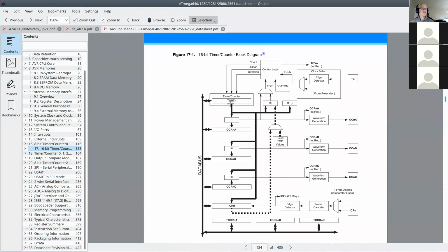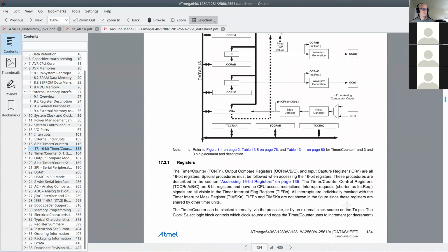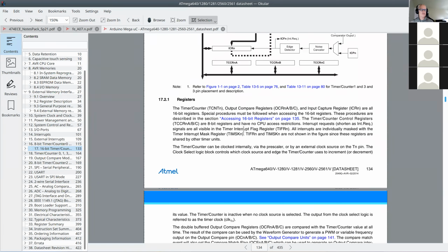And then as this thing's counting, you can freeze it and store the value exactly when a pulse comes in. So you could measure the timing of an arrival pulse very, very accurately without any software delays. That's all done in hardware. And so you could use that to make an extremely accurate measurement of when a pulse arrives for LiDAR, radar, sonar, or something like that.